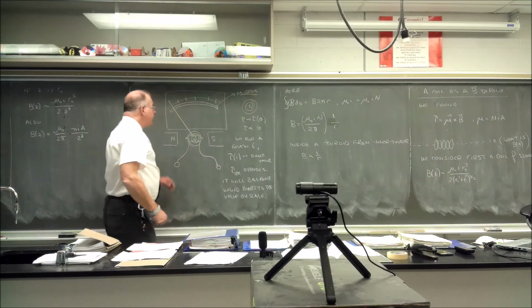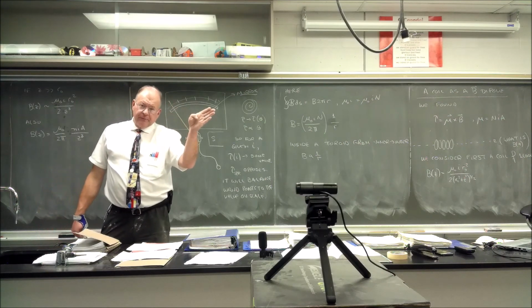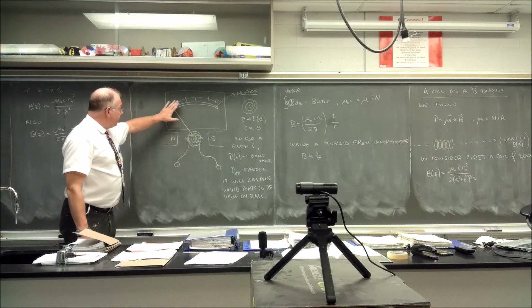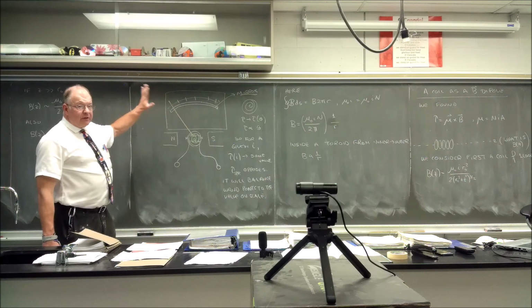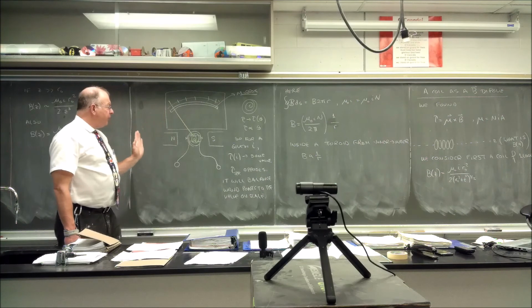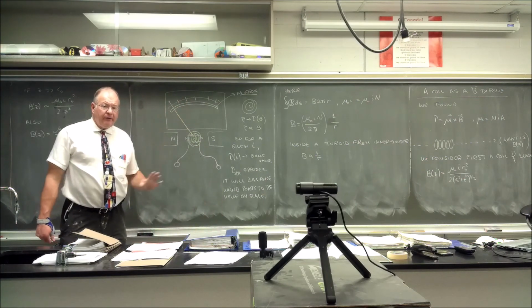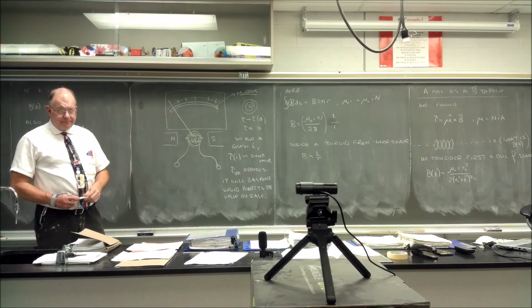And the mirror is there. If you see two needles, then you're off on an angle. And because we can't have any friction, the wand lies above the scale, doesn't scratch it, doesn't touch it. So if you're seeing two needles, you know you haven't lined up, and you've repositioned yourself so you see only one, and then you'll know that the reading you're seeing is correct.